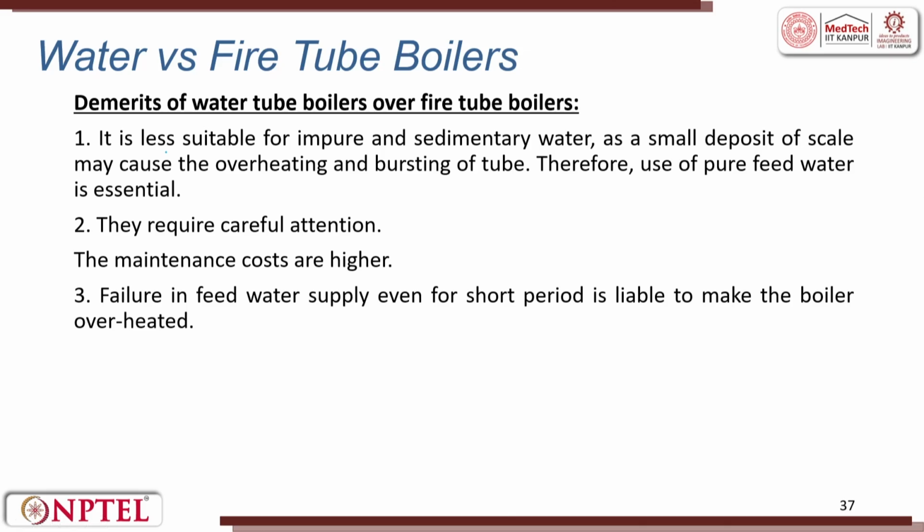Now the demerits: it is less suitable for impure and sedimentary water. They require careful attention. The maintenance costs are higher. A failure in the feed water supply, even for a short period, is liable to make the boiler overheat.